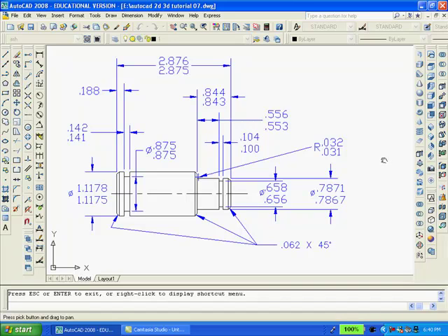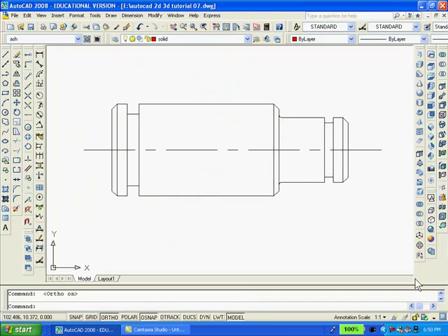Well, I just finished dimensioning the object on a layer called dimension, and you can see it's quite extensive, so perhaps a good thing I turned off the video. It's ironic, but now I went through all the trouble of dimensioning the object. Now I'm going to have to freeze the dimension layer so I can get on with designing the solid. Having frozen the dimension layer, I made a new layer called solid with the color red, and then using a polyline I'm going to trace over a portion of the object.